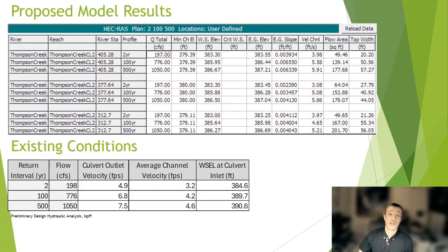The velocity of the new channel is also of great importance for the safety of the structure, as well as the future of the aquatic life inhabiting the stream bed. The results of the HEC-RAS modeling show that the velocities of the 3 stations shown in the previous slides are lower than the velocities in the existing culvert and are much closer to the average velocities of the stream as recorded by KPFF. Since the bridge channel velocities are close to the average stream velocity, some negative impacts that higher velocities could bring are not foreseen, such as scour or stream bed roughening.